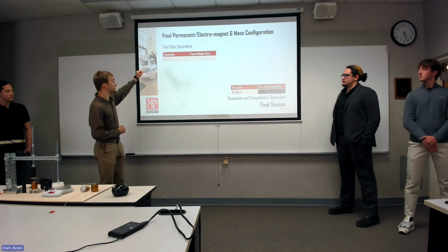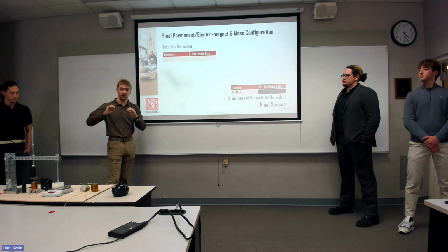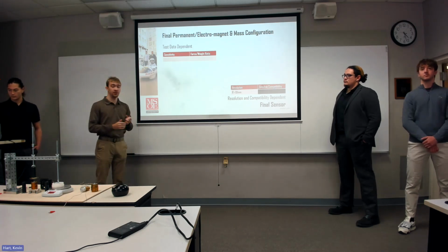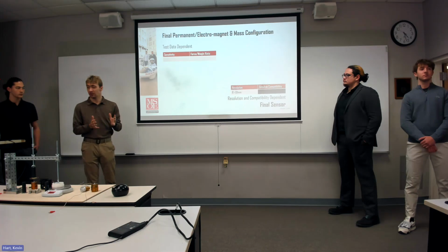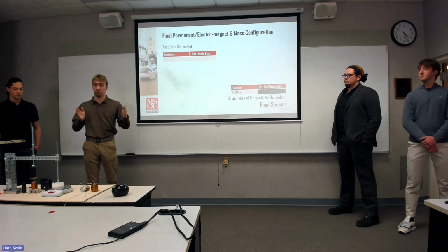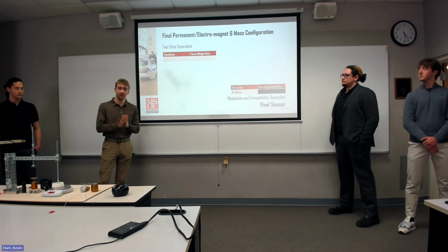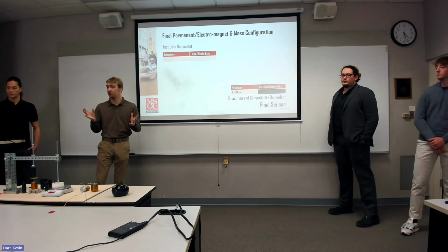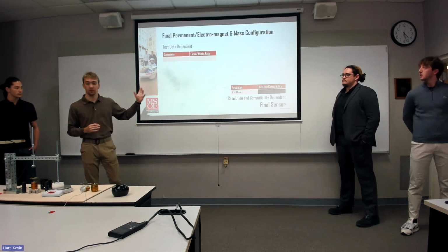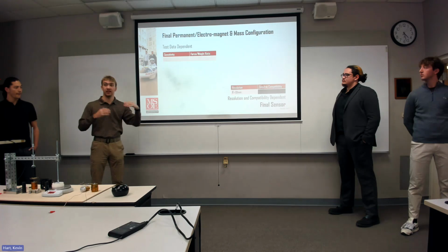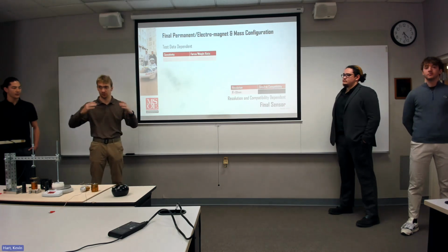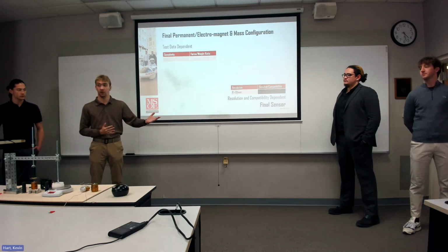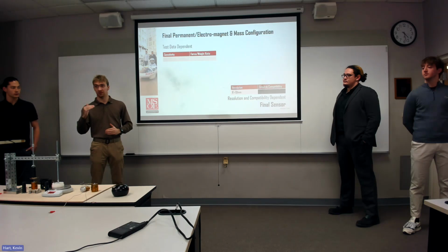The other thing is finally finalizing our main configuration with our electromagnet, permanent magnet, and washer. And that's going to be based off of the sensitivity of the system. We concluded that if we have a larger sensitivity, essentially a larger range, that would be better for us because we have more ways to vary the current and get both subtle and large changes in the force. And then also the force to weight ratio, because that will give us the nominal distance, essentially our starting point, right? If we're thinking about static equilibrium, what's our force to weight ratio, that being the magnetic force and the weight of our washer, are balanced, that's where we can start.